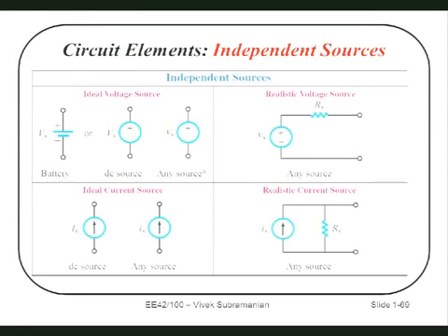Current sources, excuse me, current sources we model as a circle with an arrow. The arrow points in the direction of positive current, which means the current will come out this way. Okay? And similar rules: DC current sources are usually marked with a capital I, and any type of current source, AC or DC, is marked with a small i. Now, let's flip the problem. Let's say instead of giving you a battery, I gave you a current source, and I put one end over here and the other end of it here. What's going to happen?